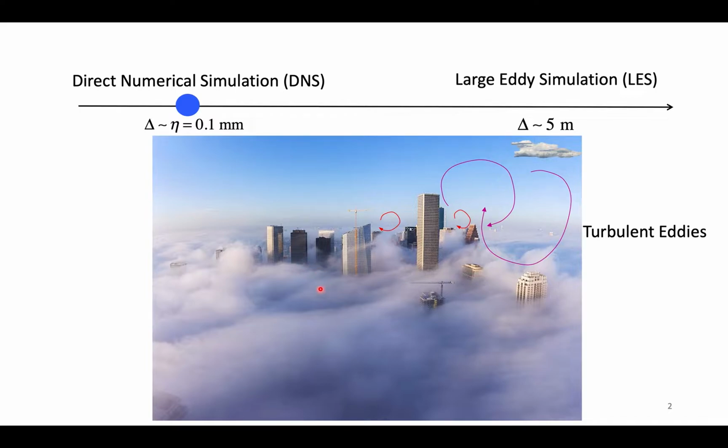We are going to have very high Reynolds number and highly turbulent flows, and you see different scales of flow, different turbulence, as you see are observed here in clouds, and also they are apparent in winds as well. In the wind structures, you see these different coherent turbulence structures and different turbulence patterns. So we have a large range of eddies here. So in the direct numerical simulation approach, we say that we are going to solve all the governing equations like the Navier-Stokes equation and continuity equation by resolving all the eddies in this flow.